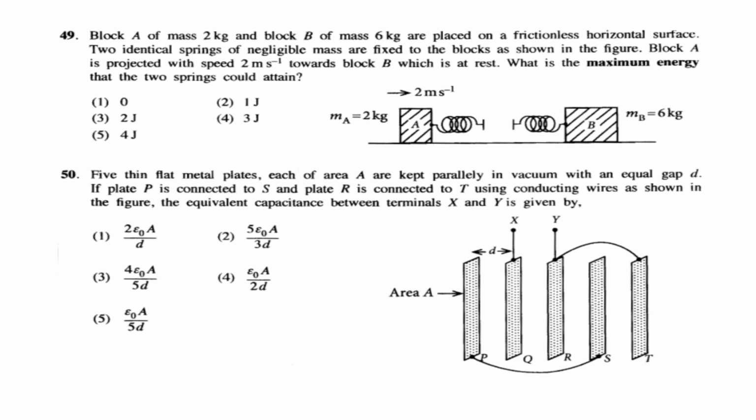When you look at the diagram, you take the 3 and 4 capacitors first. That 3 and 4 is connected to the terminal C, and since Y and B are connected together, they both are having the same potential. So we can consider that 3 and 4 capacitors are in parallel.